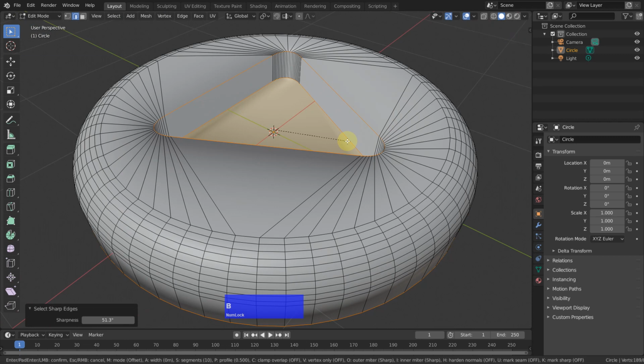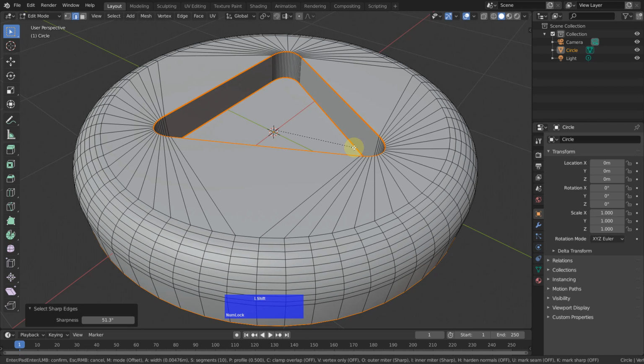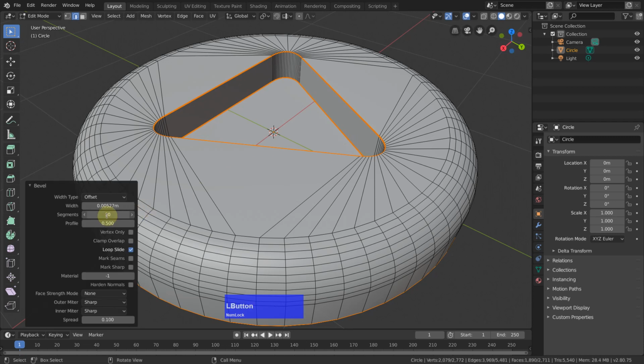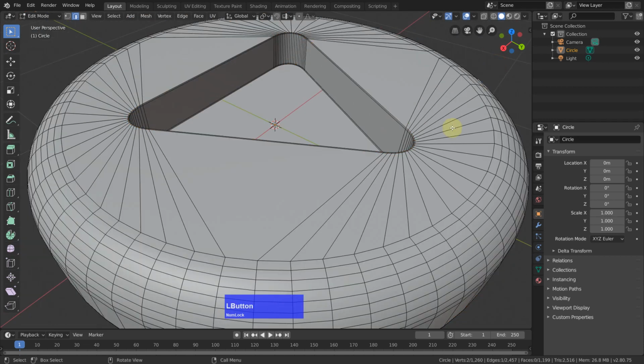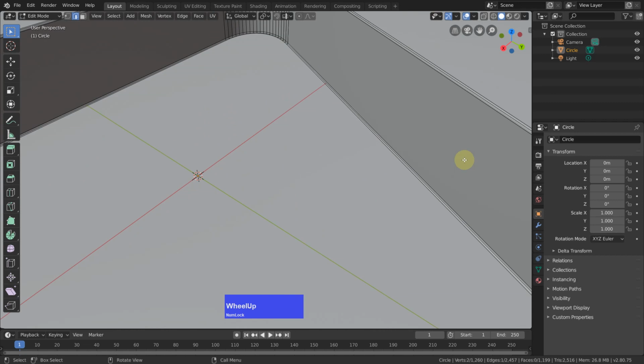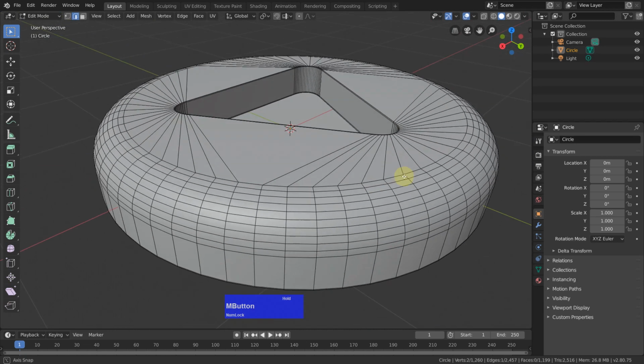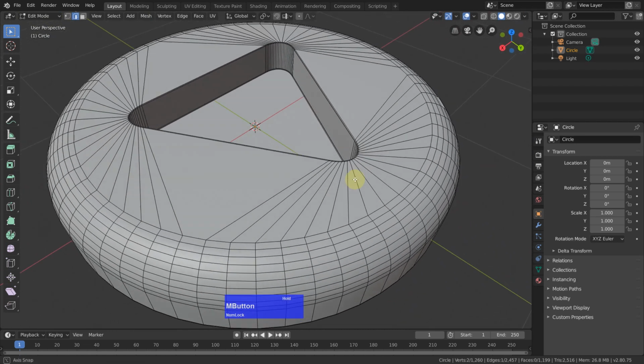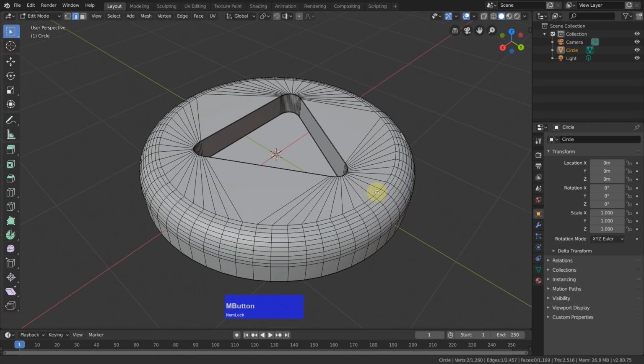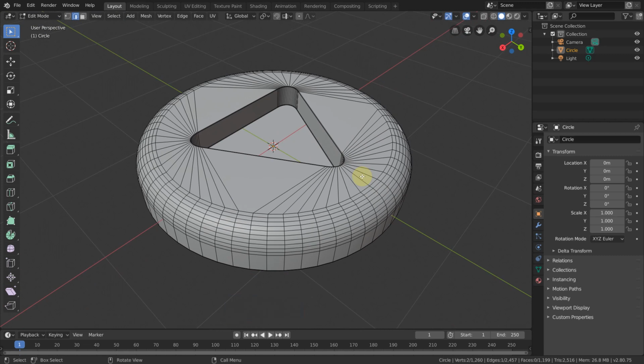So Control B. And if you want to have more control, you can press the Shift key down and then bevel this a little. And here we still have the 10 segments. I only want 2 and I want the profile to be 1. And now it's exactly like the sharp option in the bevel from MODO. So we have made something. It might be a screw or something, a special screw which is not supposed to be opened by normal consumers as we are.